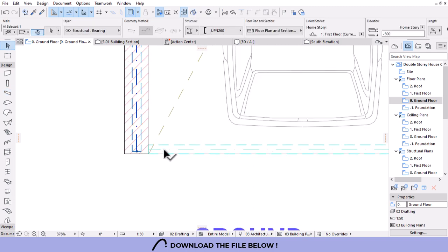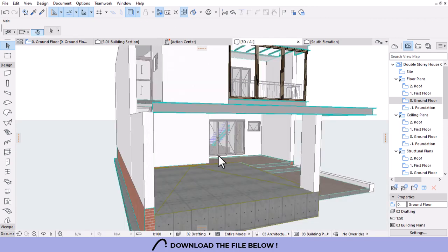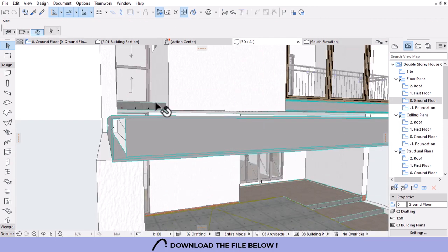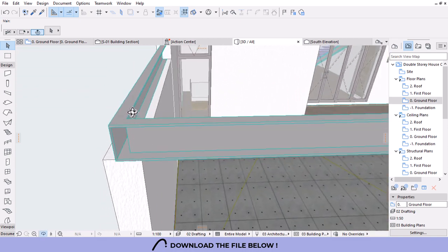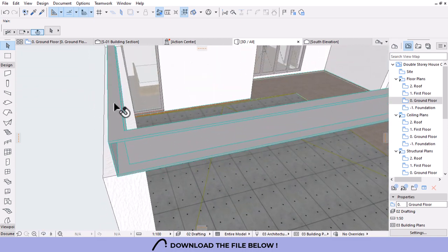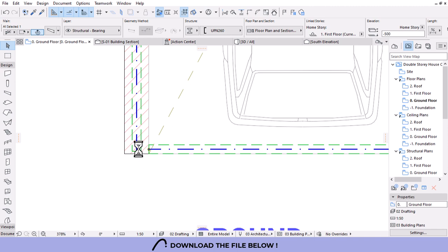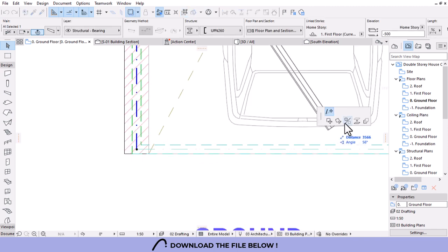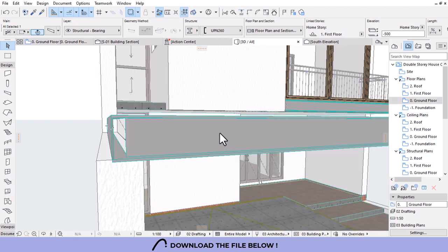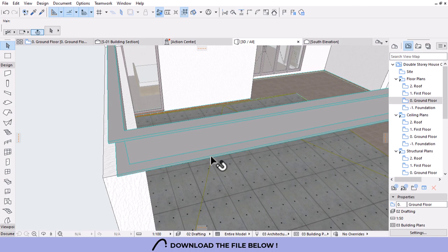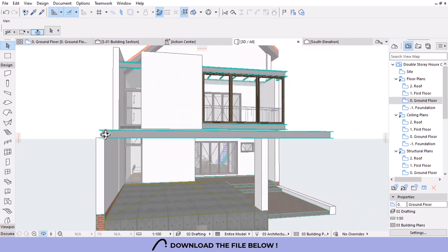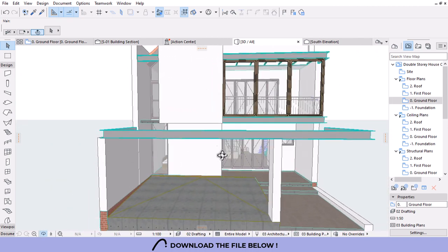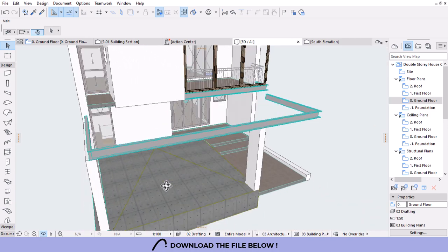Let's select this, and this one let's fillet. So check on the 3D. Let me see, it has to be the outside, the inverse. So what I'll do, select that, click on the reference line, mirror it vertical so that it can be this way. Perfect. What I want is to create an effect as if this is suspended.